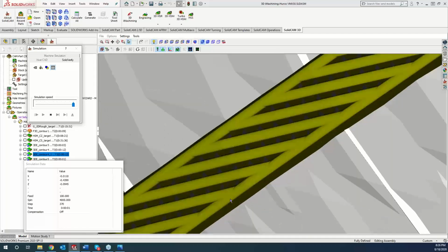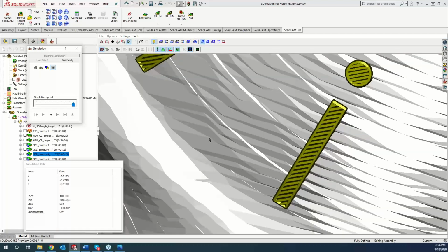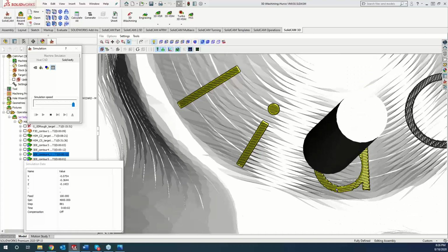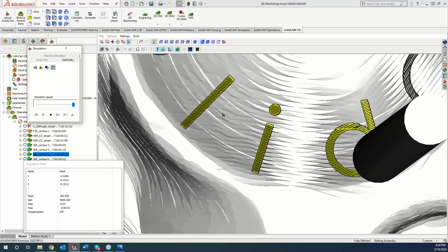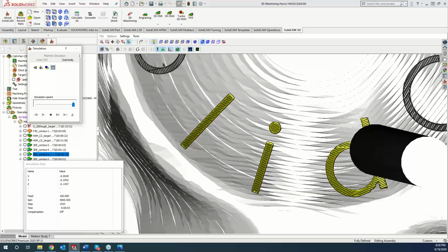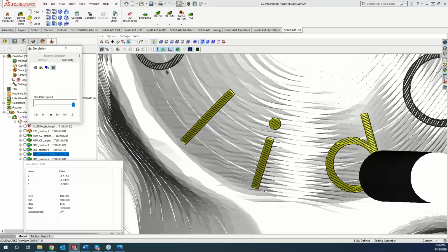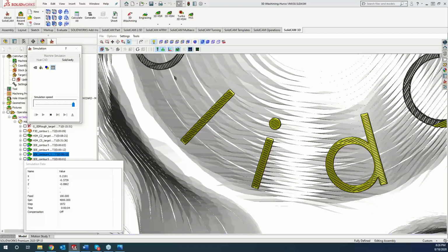It's a little tough to see, but it's giving it that full knurled looking surface in there. So we did one way, then the opposite way, 90 degrees from that original, and that's going to give us that knurled look in there.